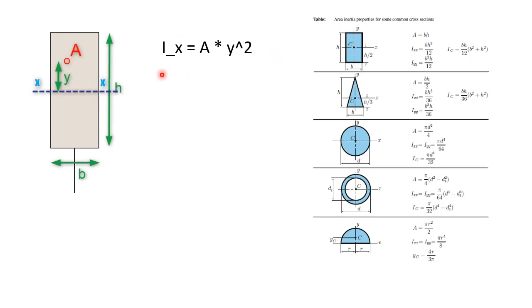Normally, when you would do this like in a textbook task, you will find some tables that do this for you or show you how it is. And for a square beam like this, or not square but rectangular, it is B H to the power of 3 divided by 12. That is useful. If you are to calculate this for any shape, there's some sort of double integral, and you will find much more of that if you search for second moment of area. But that is not what we're going into now.